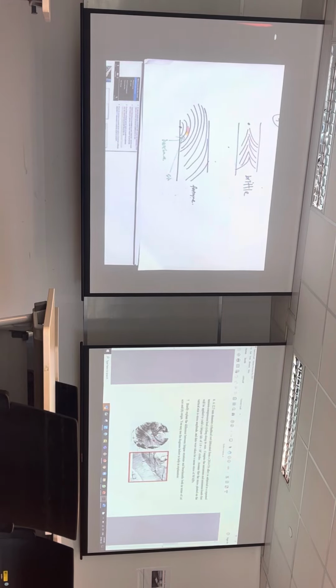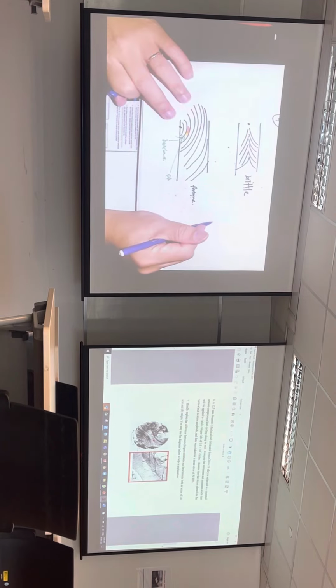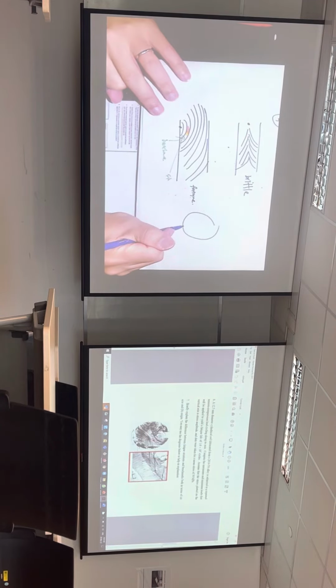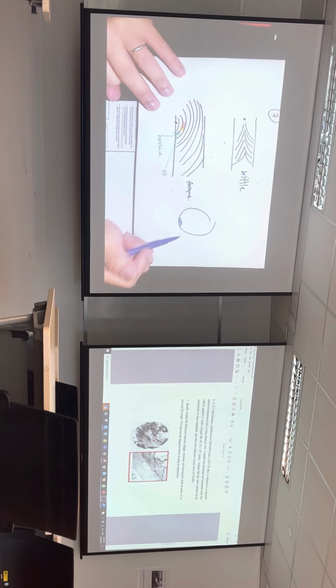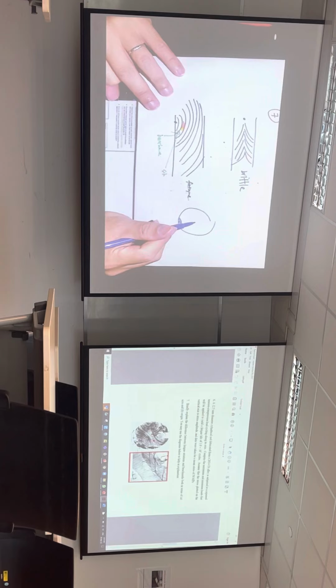And why does it fail? For fatigue failure, in very simplistic terms, if you have something here, this whole thing is way below the yield strength. If you look at this as an axle and it already has a crack, the load bearing area becomes lesser. As the crack grows with more and more cycles, the load bearing area becomes lesser and lesser.